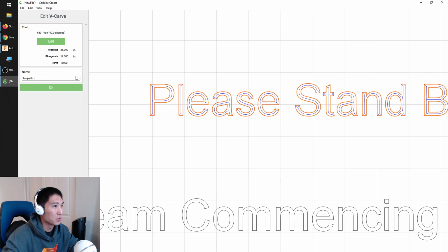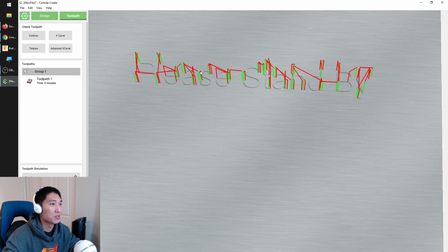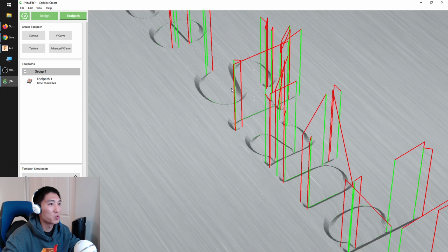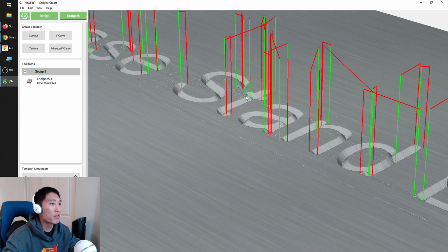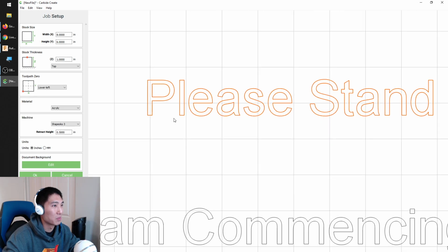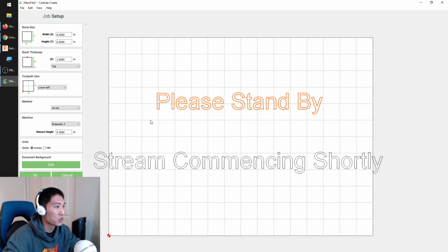the toolpath will go basically in between the contours, trying to find the mathematical center, and it works all right if your contours aren't any wider than the diameter of the V-bit. So the usual V-bits we have are about ½ inch in diameter, but if you have a pocket that's wider than ½ inch, it really doesn't work too well. So we came up with Advanced V-Carving, which will basically create an offset contour inside what you're trying to cut out.